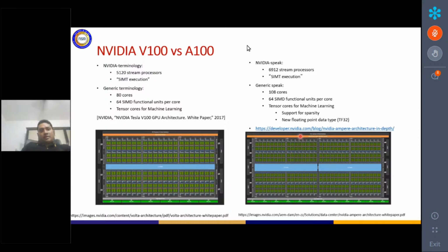Now, the basic difference of these two you can see here. Of course, in the microarchitecture level, there are differences that you will see, but from the memory point of view, you can see that L2 cache is now in the Ampere series kind of banked into two banks. Okay, so L2 cache 1 and L2 cache 2, and in the Volta series, the previous series, having only one cache memory, and that is just to increase the throughput and reduce the latency of memory accesses.